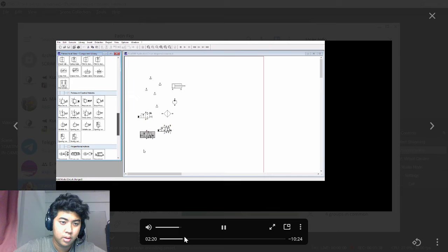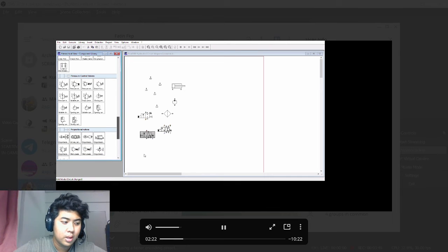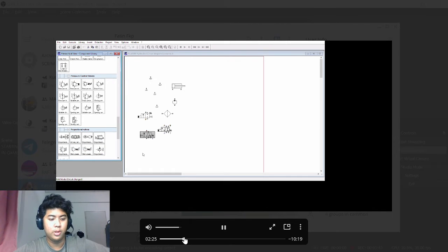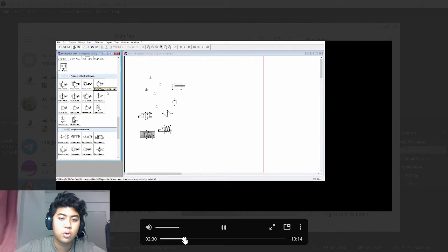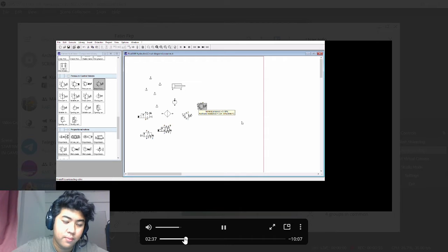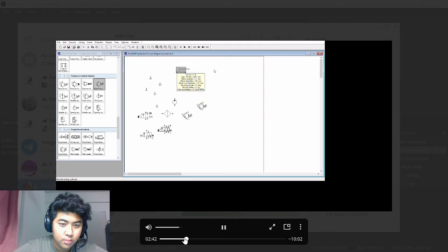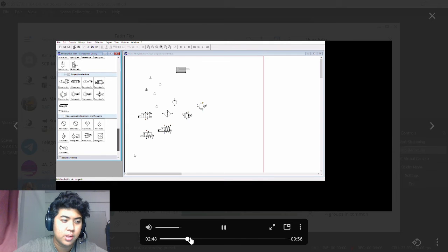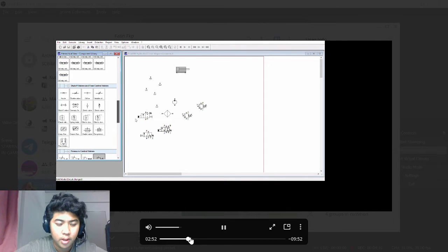After that, we will pick counteracting valves. We need two counteracting valves, and the function is to allow safe control of compressed air in pneumatic applications, which is also a shut-off valve. And lastly, we need to pick a check valve, and the function is to allow the flow of air in and prevent it from going out.